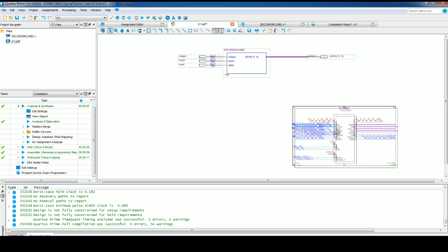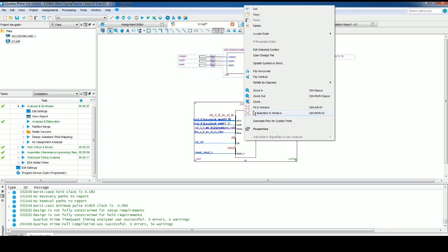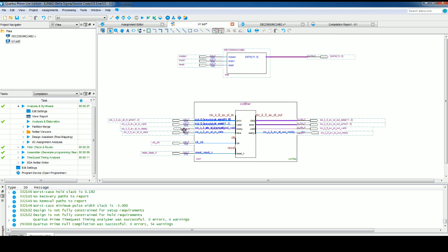You can go in and manage the different control signals. It uses a custom bus called the Avalon bus. So it's got ready and wait and signals like that. But again, if you want to shortcut it, we just generate pins for all these, run them together, and now we've got a filter built with a wizard inside of Quartus.